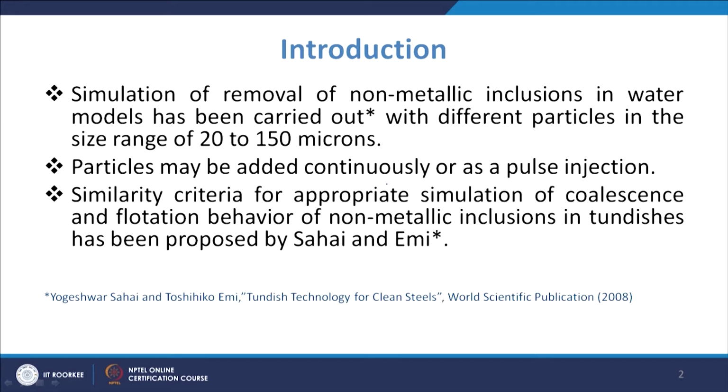So, for that you have different criteria that need to be understood, and especially as we discussed, we need to start from the velocity of fluid for the model and for the prototype, similarly the velocity of rise, that is the terminal rise velocity, which is assumed for these inclusions to go up inside the domain.